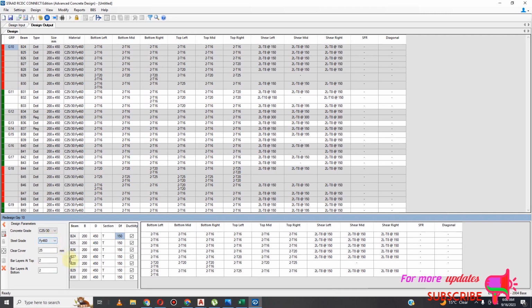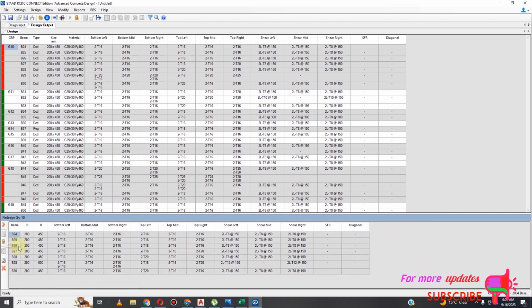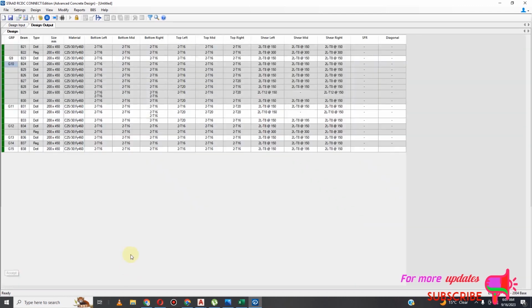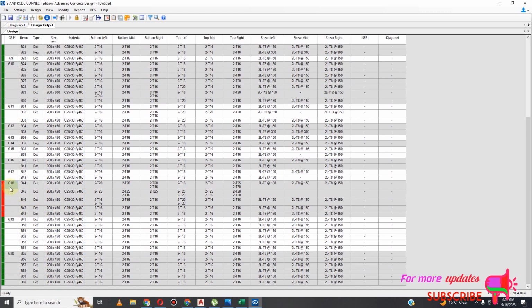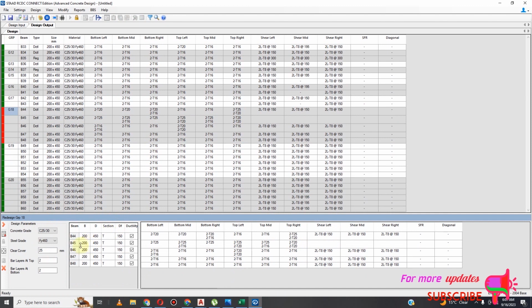So no matter what you do here, it's failing in shear, which just means the minimum spacing needs to be 100. Okay, it has passed now if you increase the depth. So that one is passing. So let's do the same. Let's try to increase the size, the cross section, for the one which is failing.